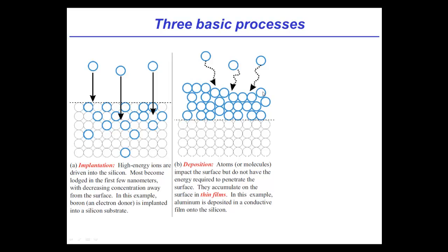For example, a very common thing that is done is called physical vapor deposition, where, let's say, a metal like aluminum is heated up somewhere else, hot enough that effectively it evaporates out, and the wafer is placed nearby so that when these evaporated aluminum atoms contact the colder surface of the wafer, they recondense, and over time they build up a layer. And there's a lot of very interesting physics and even metallurgy in the behavior of these very thin films in terms of mechanical properties and electrical properties and chemical properties. It is a very, very deep field.